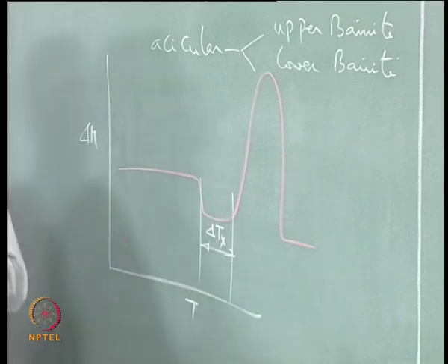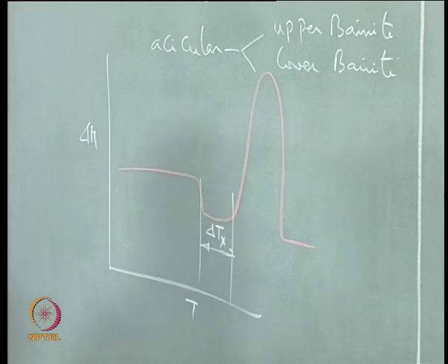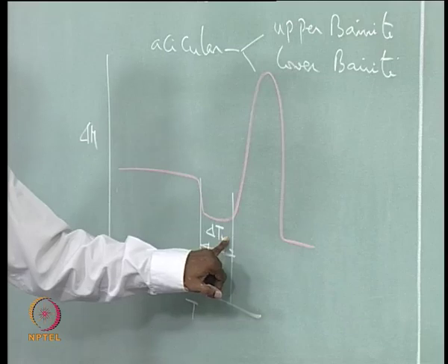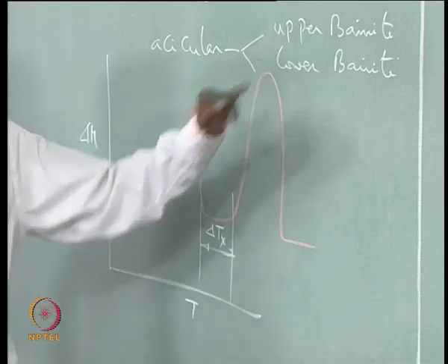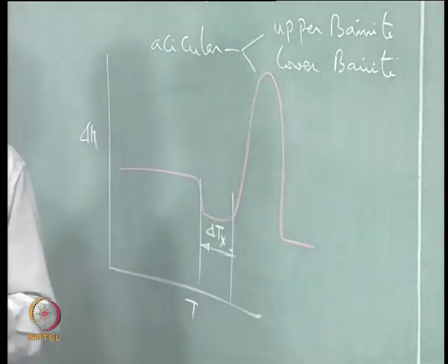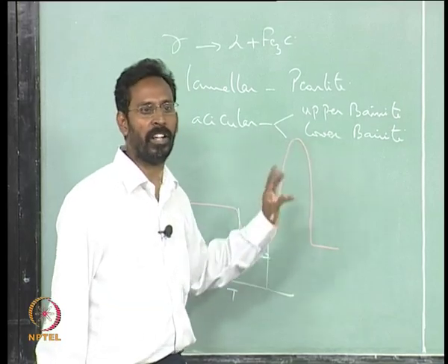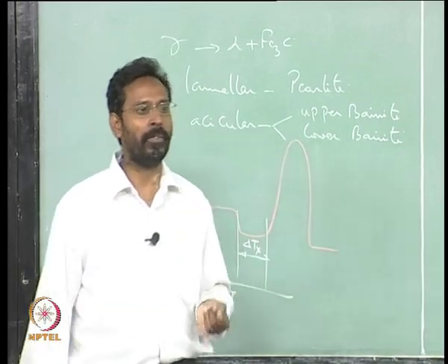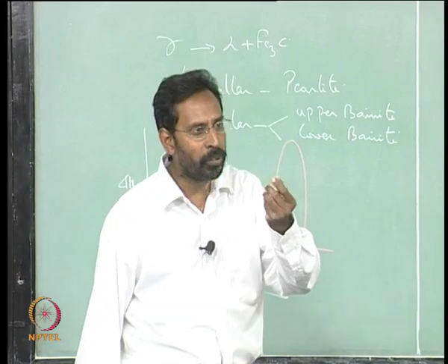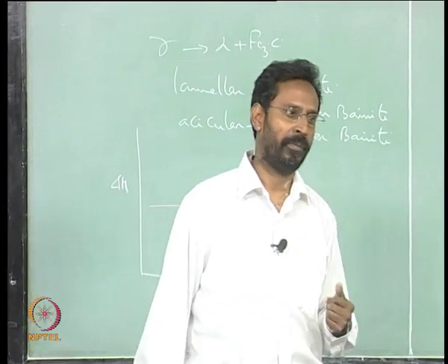In fact, all the shapes of normal glasses that we talk about also are more or less done like that. In a liquid state they do it and then freeze it. So, similarly here you can do that, shape it and then further heat it if you want, so that you can crystallize, and in fact you can control that crystallization by controlling the temperature and time of crystallization, so that you can induce nanocrystals in a glass.